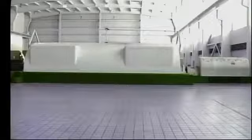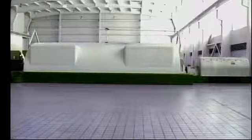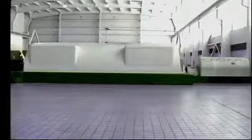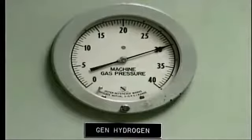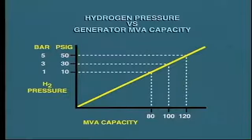The generator casing is built as a sealed unit, with the hydrogen inside the casing maintained at a pressure of about 30 psig, or about 3 bar. Not all units operate at the same hydrogen pressure, so make sure that you know the operating conditions for your particular unit.